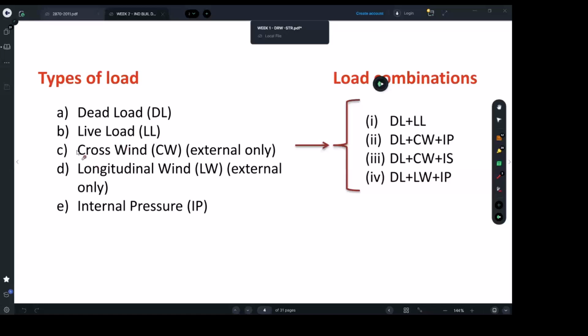Industrial buildings, especially the ones we're talking about, are very, very sensitive to wind load, right? So maybe the library projects or apartment buildings, with the block walls, like the 10-story apartment building project, got a lot of block wall, which sometimes is even over what you would need for wind load. But architecturally you want it there, or maybe the engineer wanted them there for fire rating between the apartments. So sometimes in those apartment buildings, we can easily achieve the wind load calculation, and the critical loading would be dead load, live load, right?